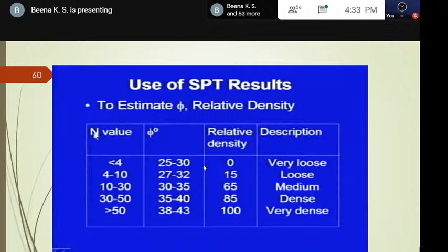If the soil is granular, apply the overburden pressure correction, otherwise no correction, and get N'. After getting N', apply the saturation correction for dilatancy if the soil is saturated fine sand or silt and N' is greater than 15, and get the N'' value. For all further design purposes, normally N'' is taken. Whenever you see the N value, it is actually N''.